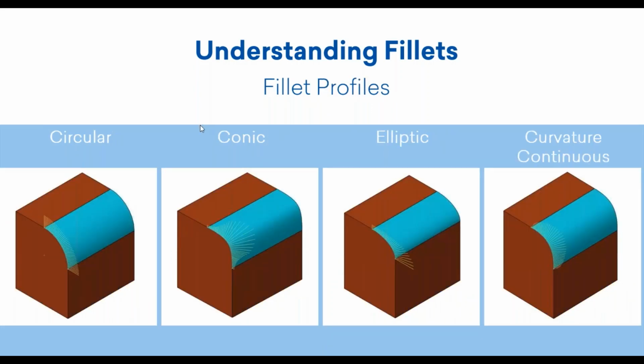I'm not going to go too much into our fillet profiles. I just wanted to include this to show that there are different types of profiles you can choose from, and that sets the curvature of your fillet as it goes from one face to the next. You can see the curvature combs on each of these fillets right here on the edge, displaying that.